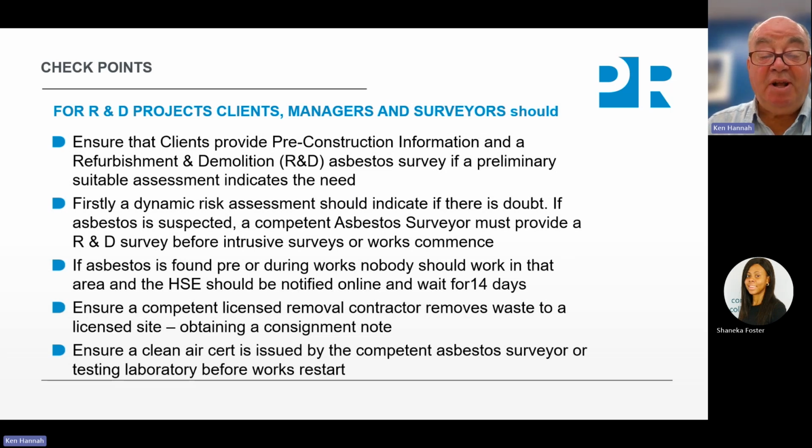You must ensure that a competent licensed removal contractor removes asbestos-containing waste to a licensed site and obtain a consignment note, which will say exactly the date, the type of asbestos that's been received, the quantity of that asbestos.